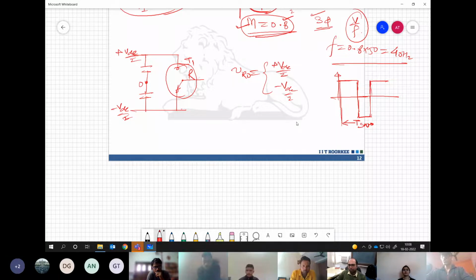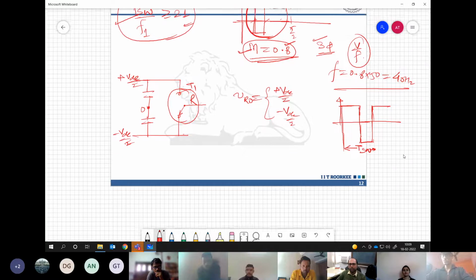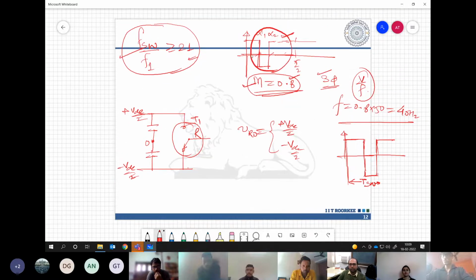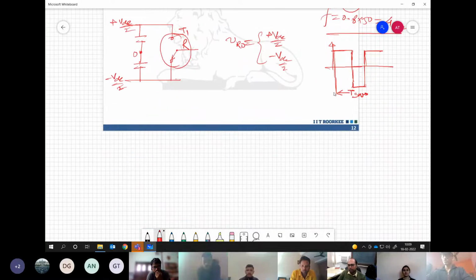Here it's not fixed. When we talk about low switching frequency, the same thing is not fixed. Switching angles could appear anywhere within this quarter cycle and so on the other half also. But here we have a more repetitive pattern. So after every TSW there has to be one notch, or within one TSW there has to be one notch. So this pattern is repeating itself several times.